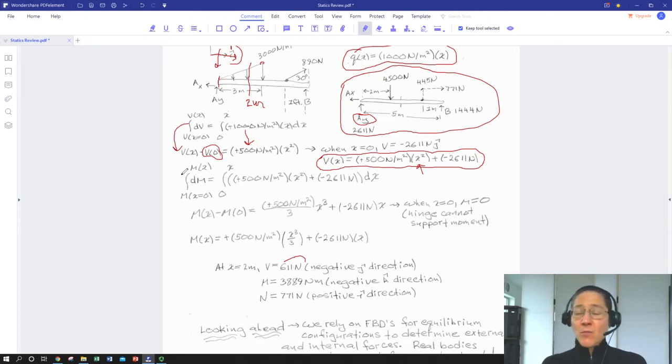So to get the moment that's being exerted on that cut end, likewise, I know that if I integrate my full expression for v sub x, between any two limits I will get the difference in the moment being applied around that cut end between any 2 points. So I do the same integration, but instead of integrating q, I'm integrating v.